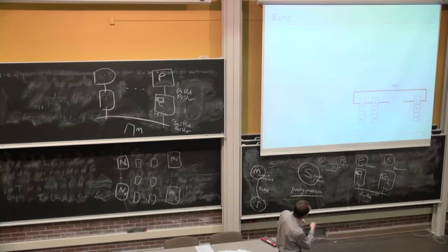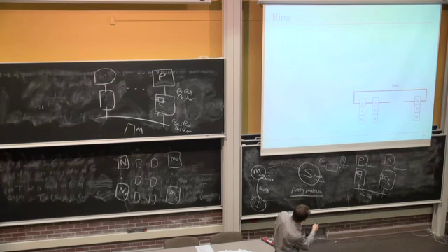The processors are connected via local links, and a ring connects all of them. Each processor is connected to the next processor, or each cache is connected only to the next cache and the previous cache, and they can still reach every other cache. And this could be bidirectional or unidirectional.